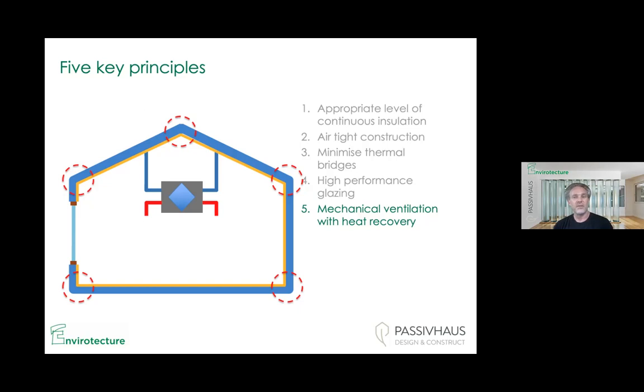And at the same time, they're pulling out all the what we call dirty air, or basically air from moist spaces, bathrooms, laundries, kitchens. And that air is getting thrown out of the building, new air is coming in, but there's a process in the heat recovery unit where they're taking the heat energy from the outgoing air and putting it into the incoming air.